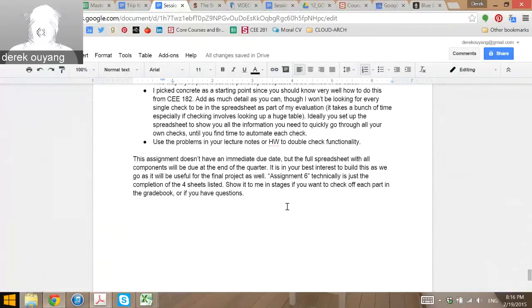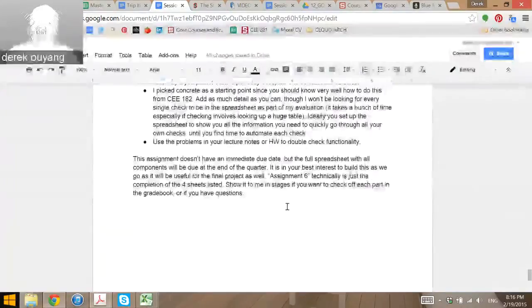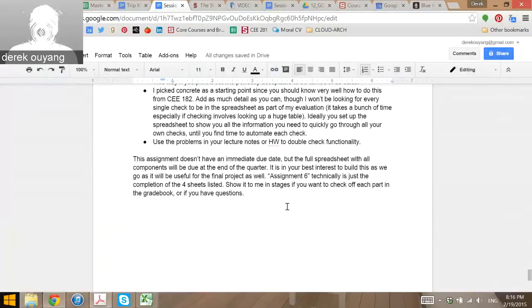So what you would probably do as a designer in this case is try to figure out the actual rib structure within this. I'm guessing that a critical image I'd want to see is the geometry without the arch section, just connecting this point to the center on all sides, and you should see a tepee, right? And then I would want to see a drawing with just the geometry of the arch from one direction. That would lead, obviously, to your max stand calcs and other calcs like that. So for the purposes of drawing, go through the exercise of perhaps taking this same view, but redoing it or overlaying it, where you're just showing the wireframe of the critical parts. That's the only exercise I can imagine.